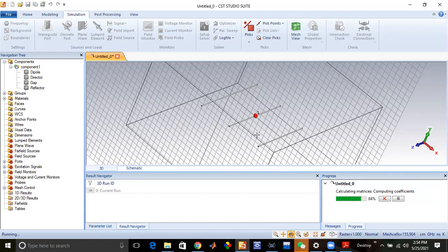For example, if this is only a dipole antenna, the radiation pattern was that. Now we have applied the reflector and director, so its shape will be like this. So after simulation we will check whether our radiation pattern is okay and whether it resonates at 1 gigahertz.